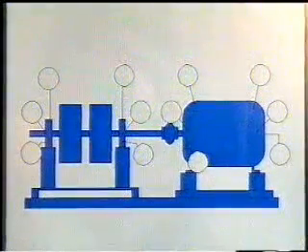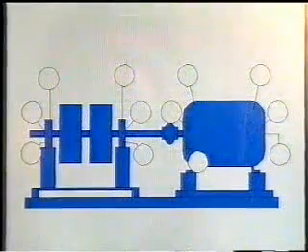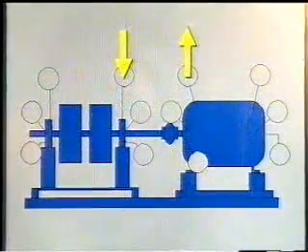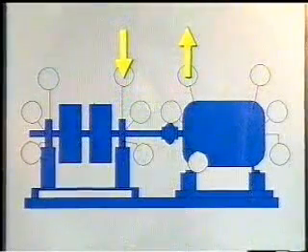Because there are so many variables, it is sometimes easier to understand the machine's movement when the phase angles are recorded on a sketch of the machine. Then, when making the comparisons, draw arrows to indicate the relative direction of movement.